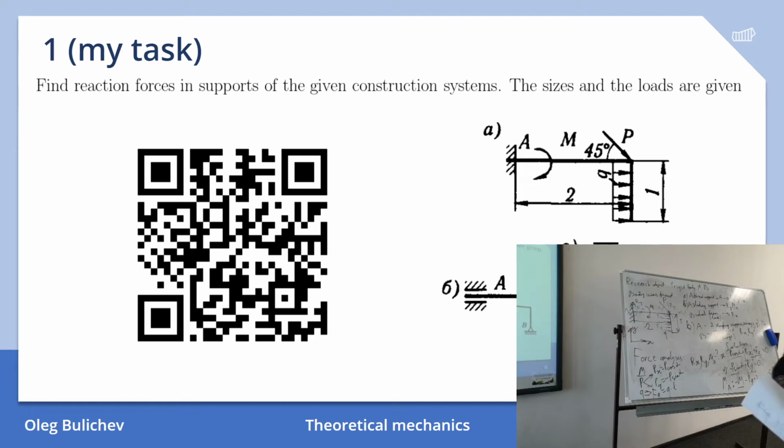Why do you have all forces on X with plus? Why do you have everything with plus? Yeah, something should be minus. Actually, maybe you assume that it is in that position, but it will appear the same. We just put minus minus, and in this case we'll receive minus there. We'll just change the direction, because it's like in velocity also. So it is okay to do like this. After this you just put numbers and you will receive the correct result.